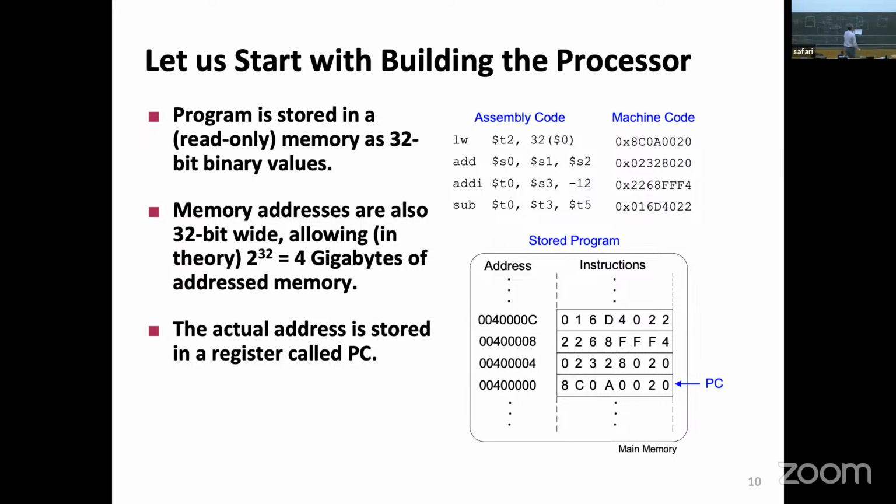So now, whatever comes out of the ALU is actually the address. This is the address that I use to find the data in the memory. And what comes out of this will get written back to the address that I already discovered. Now I will do one nasty thing so that I stay consistent to the drawing. Instead of making it like this, I will bring it back. I say, either I take the ALU output as it is, or I select between reading from the memory and reading from the ALU. So I have yet another multiplexer, and now I connect this one, this thing here.